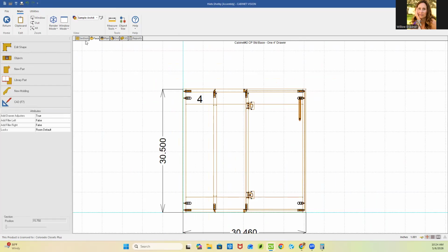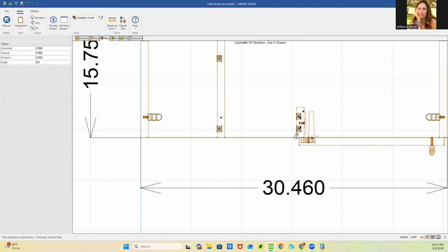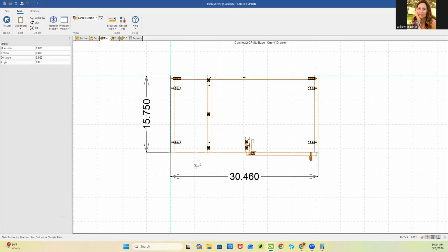So the first thing I know is that I need that partition to be exactly 14.749 inches wide, right? To fill this gap. And I want my machining to be even on a partition of that size. So I'm not going to change the width here, because that'll break my machining, like I showed you before.